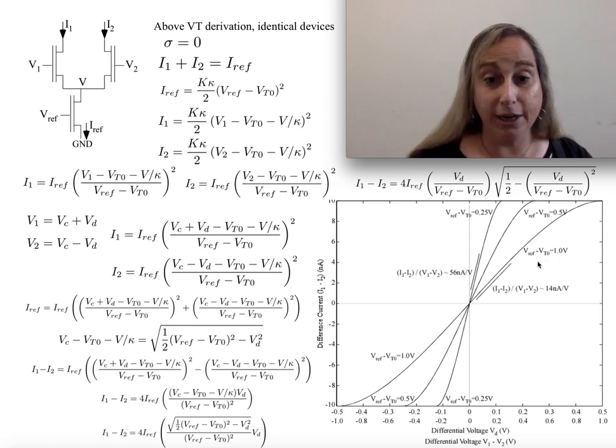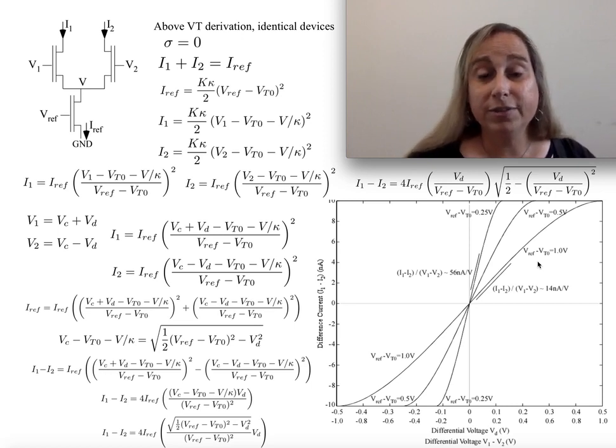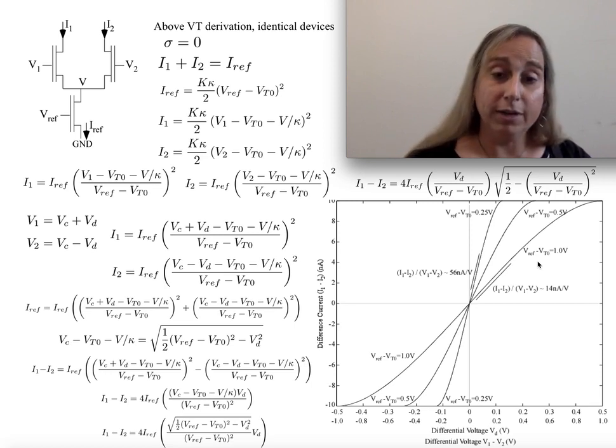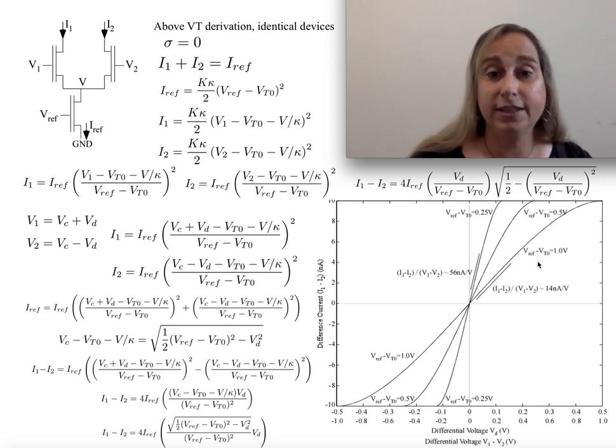So you might say the linearity changed, which could be a good thing, but you've also then decreased your transconductance. And again, this is not necessarily a bad thing, but it's something you need to be aware of. If you're trying to make something of high gain, then this is going to mean your transconductance will have decreased, and you can see different values for transconductance depending on these different slopes.